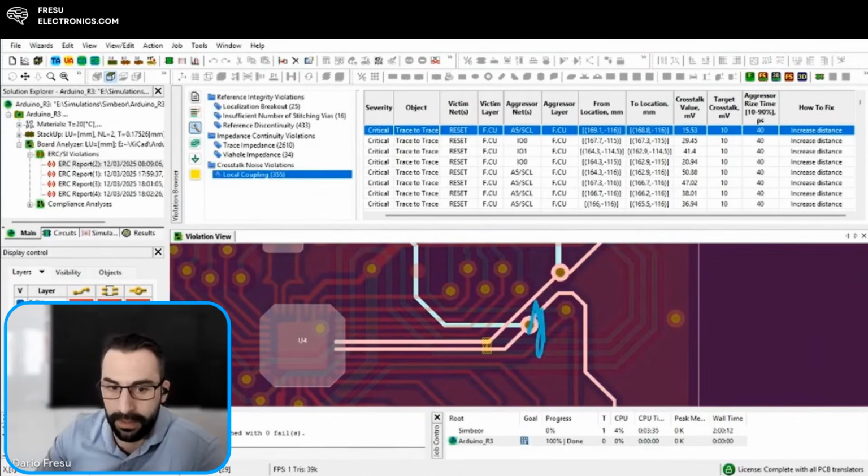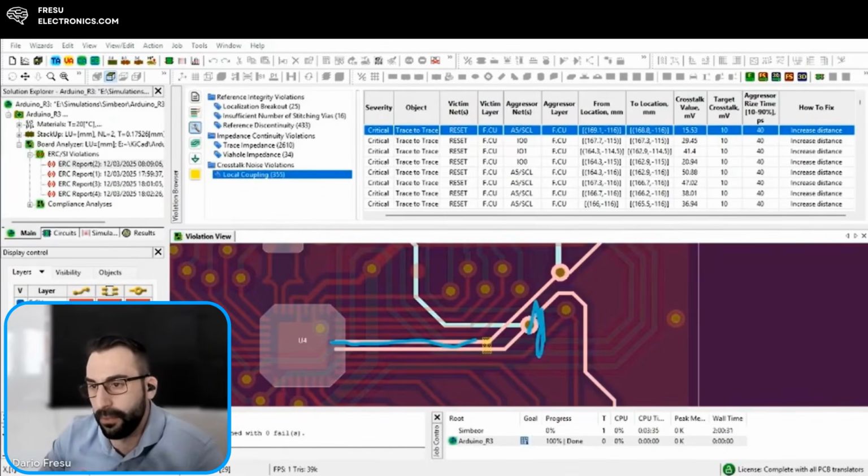If the signal is propagating along this trace and I suddenly change the width of this net, this is going to change the impedance, which creates problems in terms of impedance discontinuity, and it can cause reflection. So these 4 basic things already determine 90% of the behavior of my board in terms of EMC, but also signal integrity. And we didn't use any crazy formulas. We didn't calculate triple integrals and things like that. It's just a basic concept of electromagnetic fields.